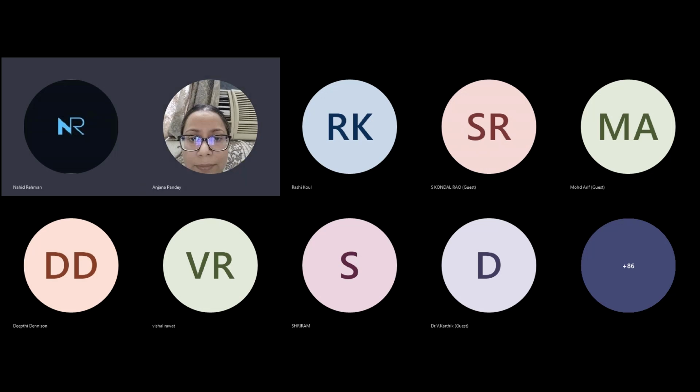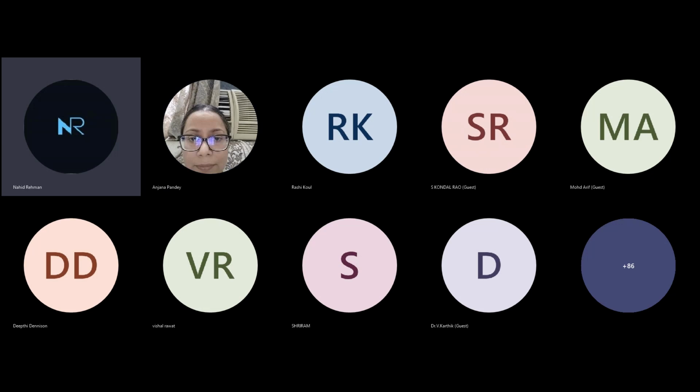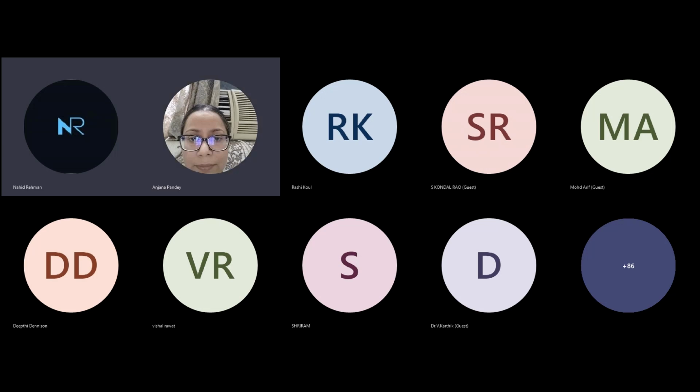Then add a robust seed culture which should have spore forming and non spore forming bacteria, selected so that a few of them are thermophilic and a few are mesophilic, so you can operate in both conditions. Your culture will be alive throughout the season.